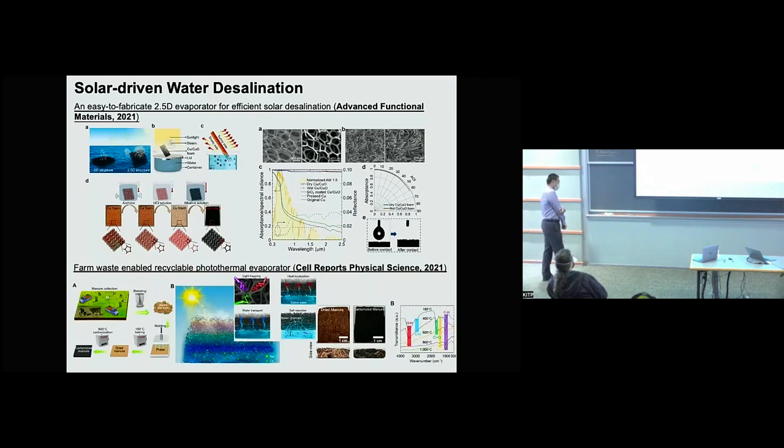People study interfacial evaporators made of hydrogels, porous materials, and some other carbonized carbon foams. And also people study different geometries in 2D form and also in 3D form. 2D form is like a thin film evaporator, or a multi-layer structure, but actually all of these materials are floating at the water interface. We treat all these structures as 2D.